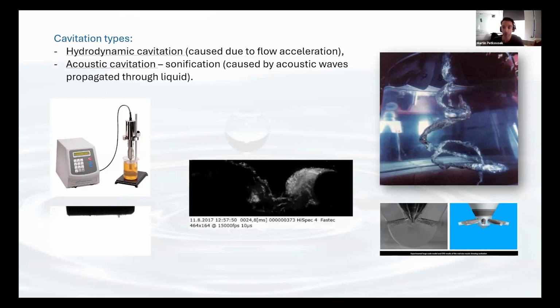Here on the right, we can see a cavitation vortex generated at the outlet of the Francis water turbine. And this vortex, for example, is causing serious vibration on the whole turbine. Here on the video, in the middle, we have a cavitating flow in a shape of von Karman vortex that is generated behind the cylinder in the flow tract.